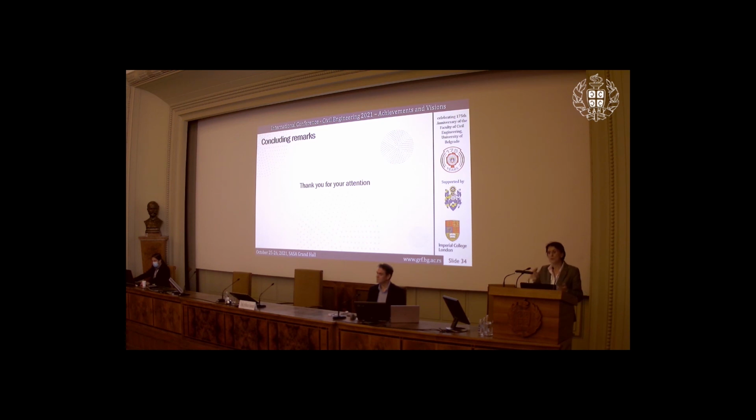And that is where the failure can or cannot be initiated. So if we could have in slopes a continuous measurement of pore pressures, I think that would do a lot for any sort of early warning. But it's something that you need to convince industry is worth putting in and monitoring for a long period of time.